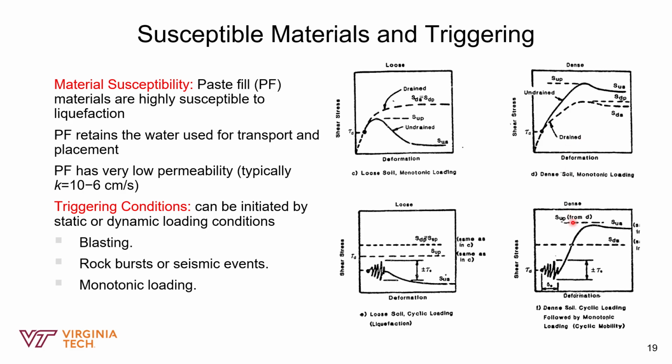And under cyclic loading, the pore pressure increases, but the tendency towards deformation is resisted by the soil mass stiffening and increasing shear stress.